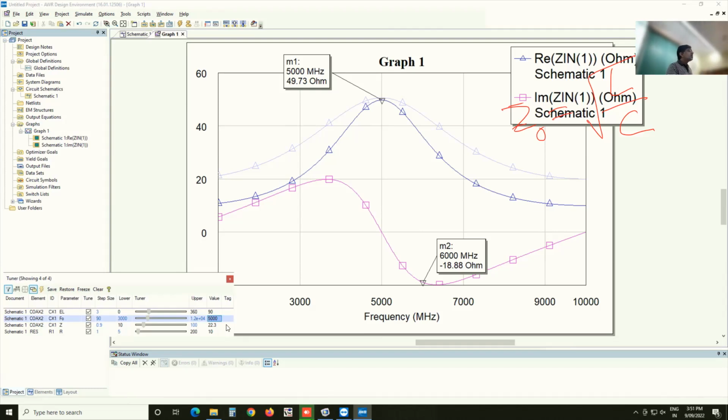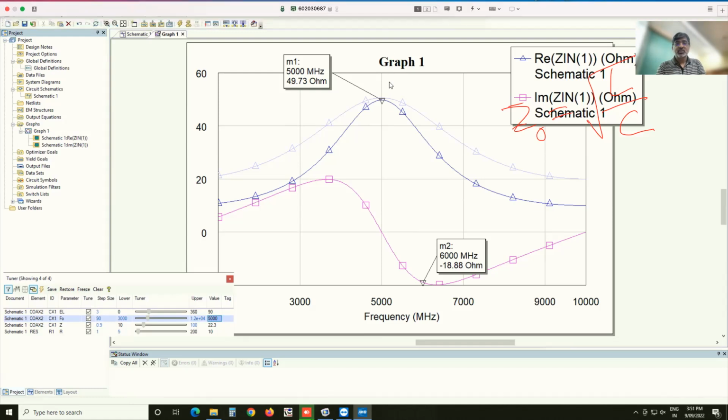What does smoothly changing mean here? Basically, when the dimensions are changing, the L per unit length and C per unit length are changing. If they're changing in a very slow and continuous fashion, then at every point, the waves will not see a very different medium in front of them, and hence they will not reflect. So in the next lecture, we will begin with this viewpoint of multiple reflections when we have these sections, which will also come back to the same impedance transformer formula. Let me just quickly flash that.